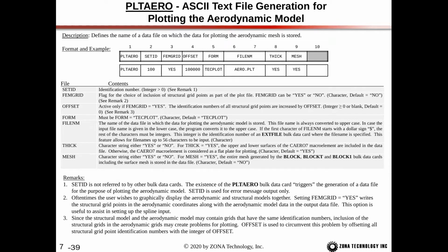So I do recommend having at least one PLTAERO card where FEMGRID equals yes, so that you can verify that the structural grid points overlap with the aerodynamic model. Offset is active if FEMGRID equals yes.